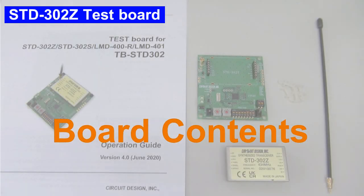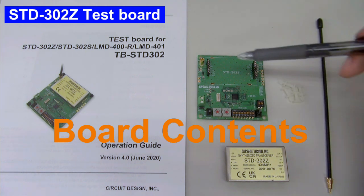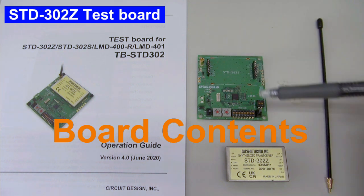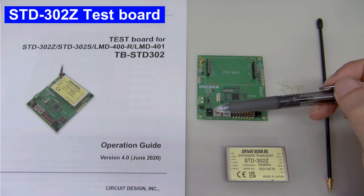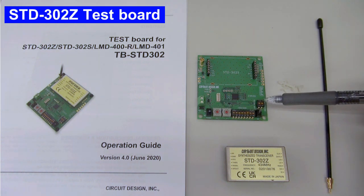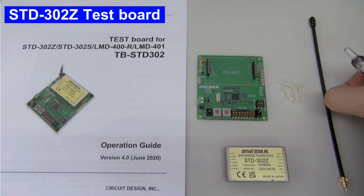So what is included? A CPU on the board containing the PLL setting lookup table. This is the antenna socket, the space for the module, power supply for the module, power switch, channel selection, band setting for the module, PN9 modulation switch with data rate setting, transmit receive set, board stands, antennas for 434 MHz and 869 MHz.